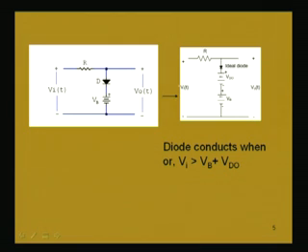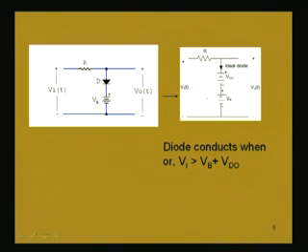If you remember, what we have done earlier is that when you want to replace the diode by its equivalent model, we draw the battery showing the drop Vd naught along with the ideal diode. The ideal diode is just to show the direction of the conduction current in the diode. So, the same circuit we are equivalently drawing again by using this constant voltage drop model Vd naught. Others are the same, Vb is there, this source battery is there. So, the input voltage is sinusoidal, again we are assuming.